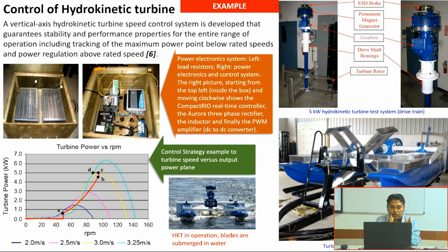Now if, with a similar velocity, I increase the turbine diameter, what will happen? It may happen that the topmost power generation value is here, corresponding to a certain RPM, and the only thing is that due to the bigger diameter, the curve may become almost a single flat line. So that you have to check: which type of nature of curve it will produce because of the change in diameter, or the change in river velocity, or the implementation of some techniques which will enhance the flow. So those things will be there.